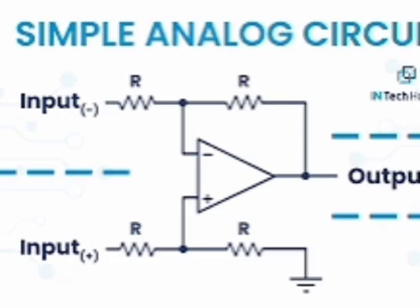IDC of bridge circuit based full wave rectifier: 2 Im by pi equals VDC by Rs plus 2 Rf plus RL. VRMS of half wave rectifier: Vm by 2. VRMS of center tap based rectifier: Vm by root 2. VRMS of bridge circuit based full wave rectifier: Vm by root 2. Ripple factor of half wave rectifier 1.21; center tap based full wave rectifier 0.48; bridge circuit full wave rectifier 0.48.